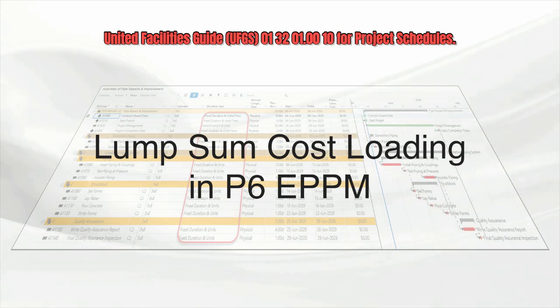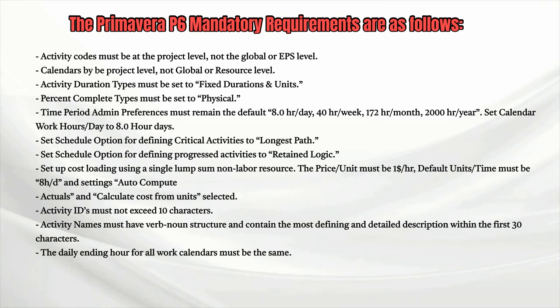P6 Professional includes a program for converting XER files to SDEF format. P6 EPPM does not. P6 EPPM XML files will require P6 Professional to convert to XER format, and then the XER to P3 per SDEF project conversion software to translate to SDEF format. Again, we want to demonstrate the lump sum cost loading for a web client connection to a P6 database. The Primavera P6 mandatory requirements are as follows.